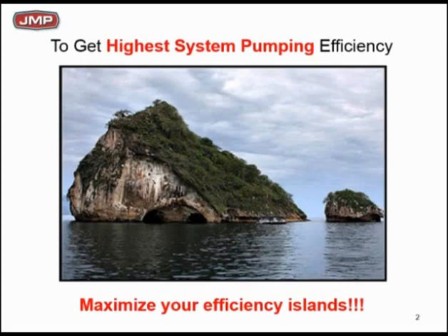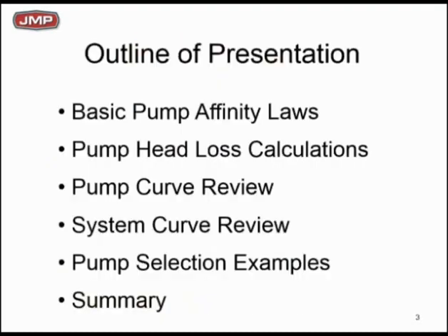It's okay to look at BEP, which we'll talk about in more detail, but in reality, we're moving around on the pump curves. So we want to look at efficiency islands or efficiency areas and have the biggest efficiency islands we can, realizing that our actual pumps are moving back and forth and they're not at any one specific efficiency. So it becomes the average efficiency over the range of the pump that we're interested in.